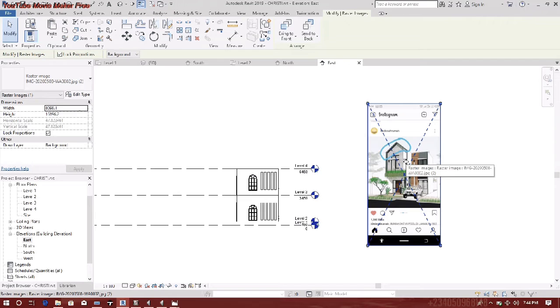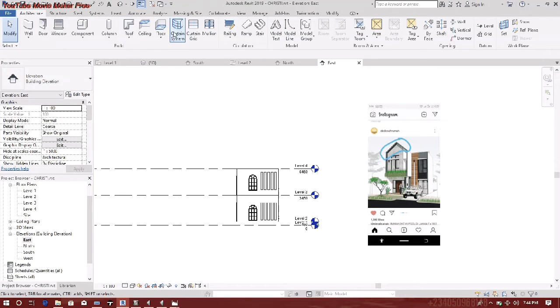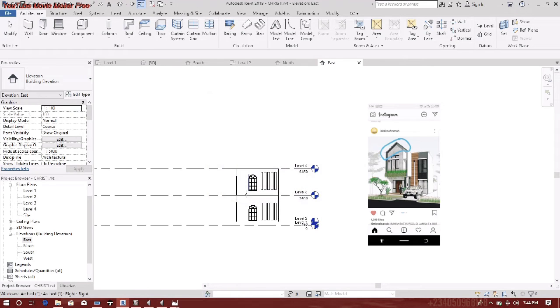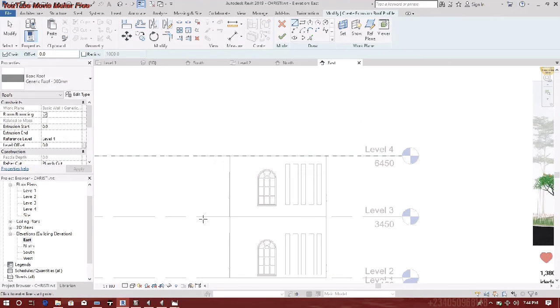So you can use extrusion and you can use roof extrusion. So how do you use roof extrusion? You come to roof, you see roof extrusion. When you see roof extrusion, select none, so you'll be able to pick a work plane, so you are working directly on this surface, and you click on OK.